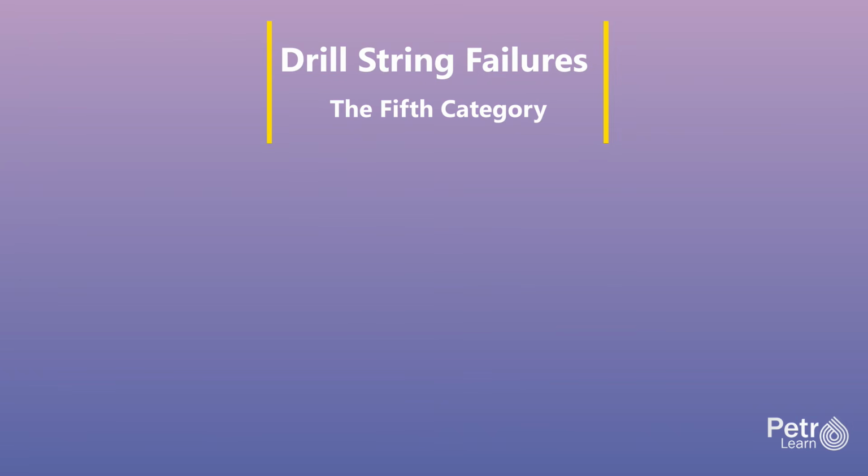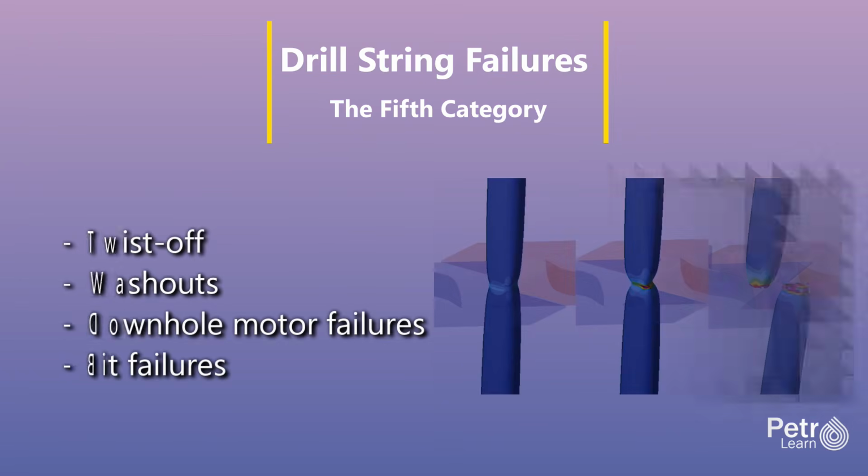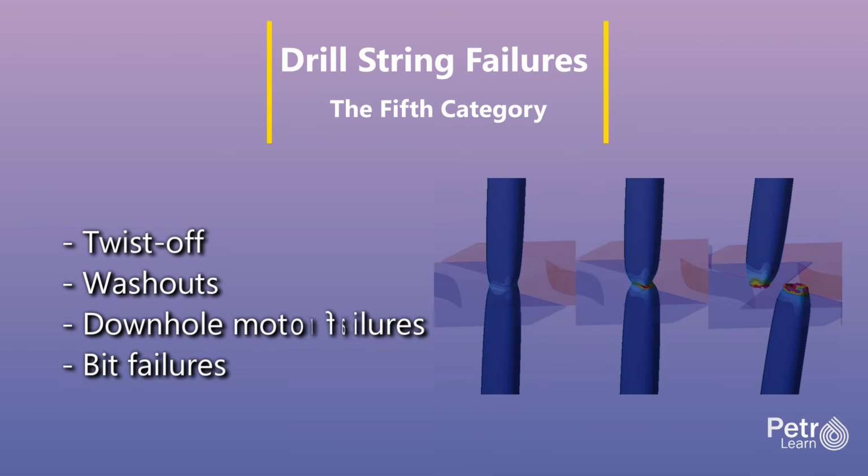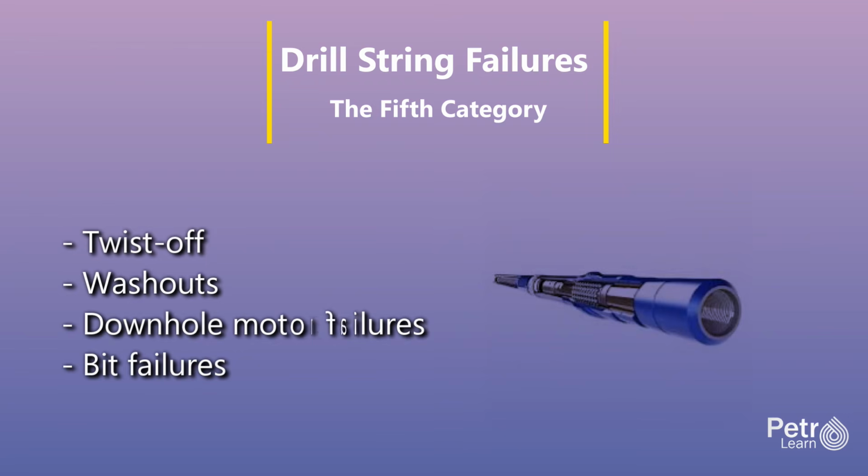The fifth problem area is drill string failures and equipment problems. Twist-offs occur when the drill string fails in torsion due to excessive torque combined with tensile stress, typically at a worn tool joint or in the transition zone between drill pipe and drill collars. Washouts develop when erosion from high-velocity fluid flow or vibration wears a hole through the wall of drill pipe or a tool joint. A washout is detected by decreased pump pressure and reduced return flow rate, as some mud is exiting through the hole in the string instead of going through the bit.